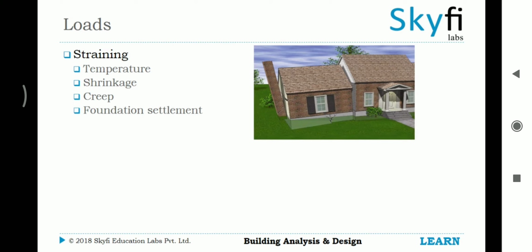Foundation settlement is the sinking of the foundation inside the soil, which results in the sinking of the entire building. This occurs if the foundation is not designed strongly enough to complement the bearing capacity of the soil, and might also be due to the structures and foundations in the neighboring area.